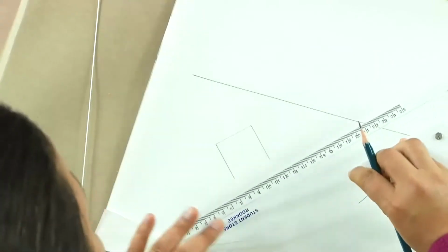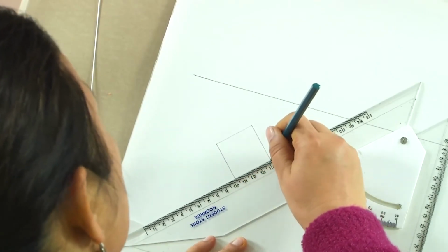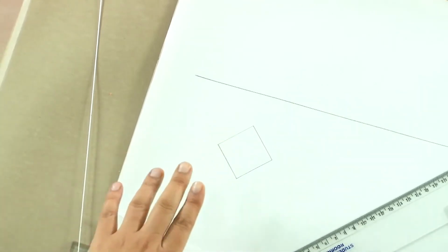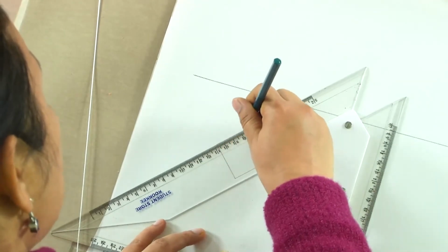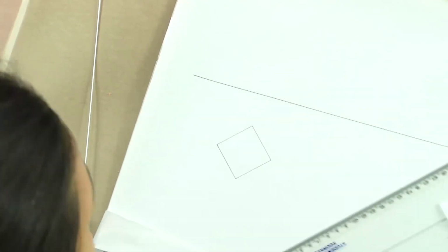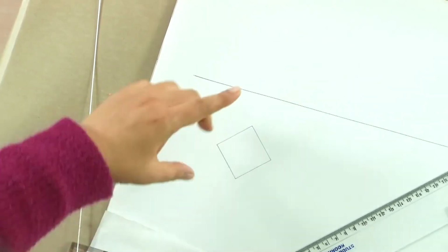This is the square which we are assuming. Since it has only one point in HP, that is why we have taken it as a diamond, or it is rotated. Otherwise, when we start to incline it, it will become very difficult for us to incline it about one point if we keep it straight. Now, let us take the projections of this square.